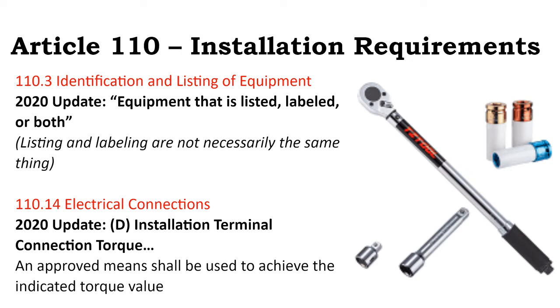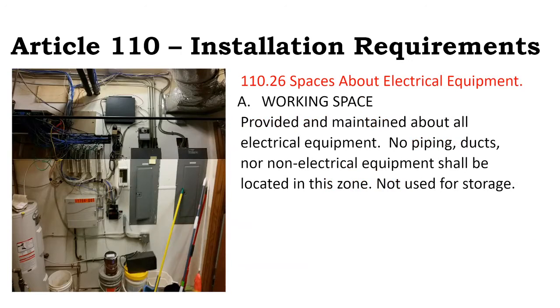You don't want to crack any chip boards. You don't want to bust the actual cable so that it pushes itself out of the way, but you still need to get it tight enough. A professional installer might err on over tightening things more commonly than under tightening them, but an amateur installer is going to under tighten them. And they don't have the hand strength of a worker.